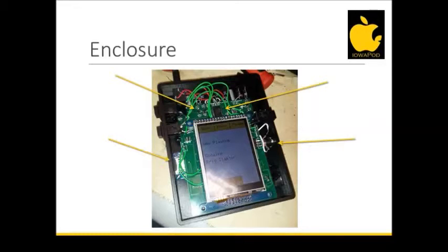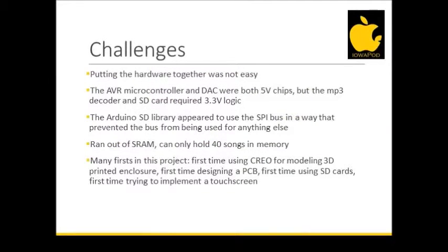So this project had many challenges. Simply assembling everything was difficult in itself because everything had to be soldered by hand, and because we used a microcontroller with pins that had a 0.5 millimeter pitch, it had to be done under a microscope. It also took us a while to figure out that MOSFETs would work well for the level shifting. We initially used RC voltage dividers, but we weren't happy at all with the transient response or the wasted power.